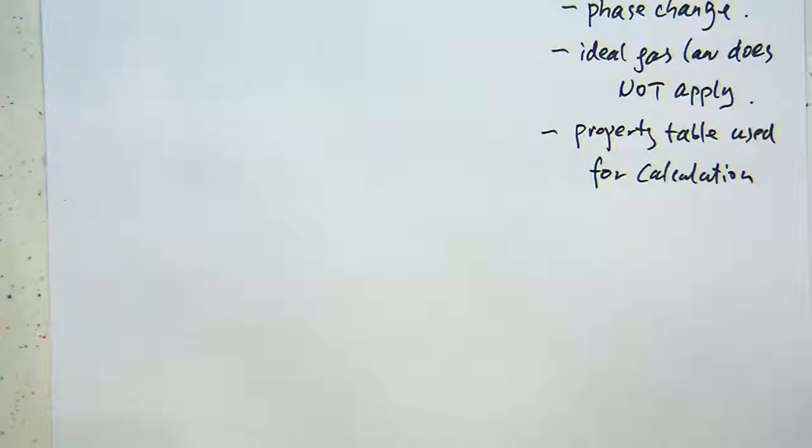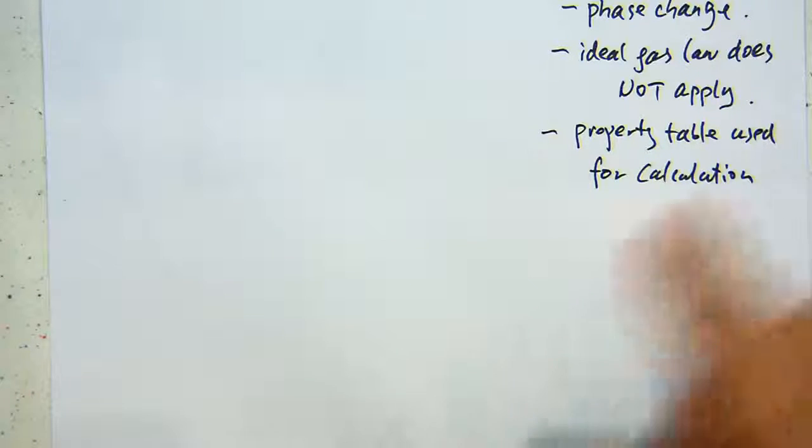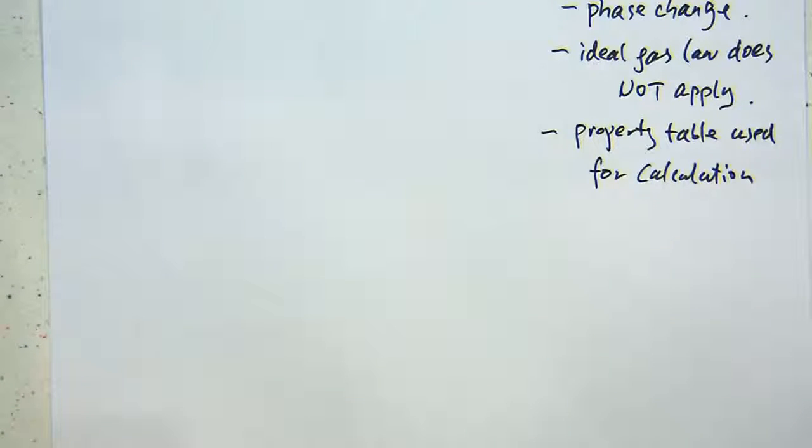So you go to this reference data and find the entropy, specific volume for the given condition, right? So you need to use a table extensively in order for the calculation. And certainly there are different tables being used for different phase in terms of saturated mixture, vapor, and even pure liquid. Right. So this is something we want to be aware of.